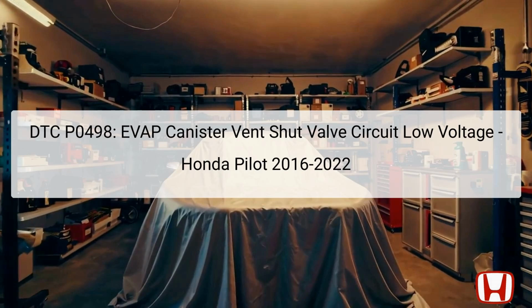The Diagnostic Trouble Code, DTC P0498, indicates a low voltage condition in the EVAP canister vent shut valve circuit. This fault specifically pertains to the vent shut valve, a crucial component of the evaporative emissions control system, which prevents fuel vapors from escaping into the atmosphere. The EVAP system is designed to capture and recycle these vapors, thereby minimizing emissions and improving vehicle efficiency.